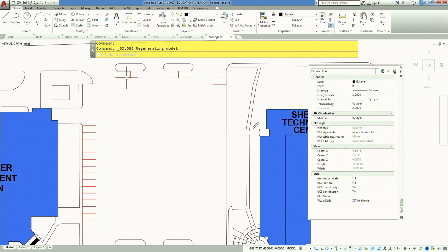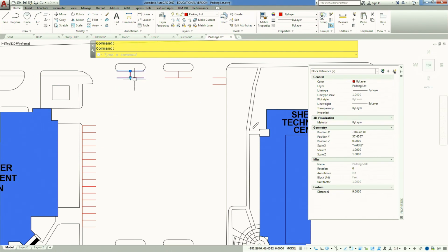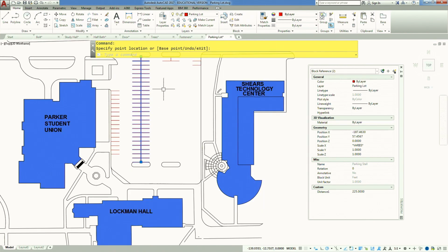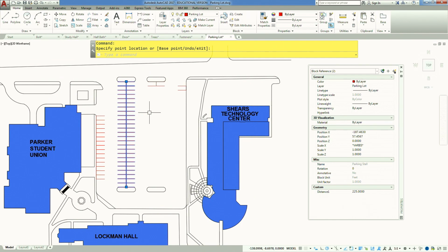And now when I grab one of these, I can actually do 2 at once here on this one. I can grab this grip, and now you can see that it locks on to the increments. I've also gotten rid of that other grip that allowed me to goof that up, so now I can very easily finish out my drawing here. So again, linear parameter. This time it was an array, and then we can control those values using our properties.